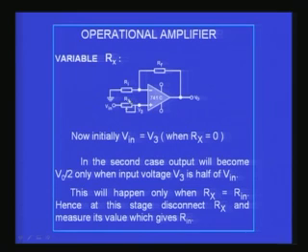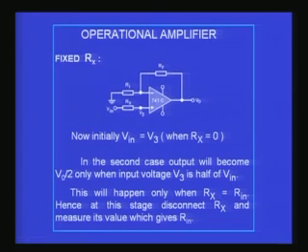So, any measurement will have to be done in a passive condition. That means you should remove the Rx, preferably, and then measure using a multimeter, thereby you would be able to get the input resistance of the amplifier. Now, usually the input resistance of an amplifier like a non-inverting amplifier can be very high, sometimes 100 megohm, 50 megohm and things like that, because the open loop gain is a very large value, as we have already seen.